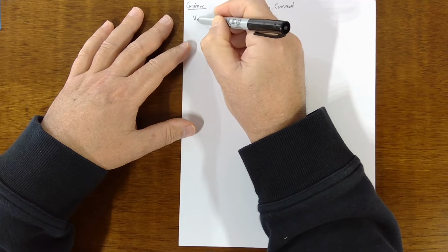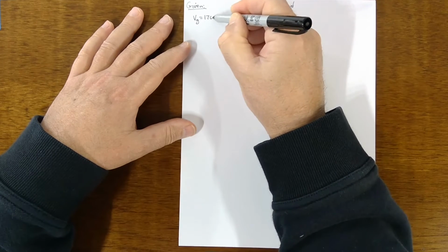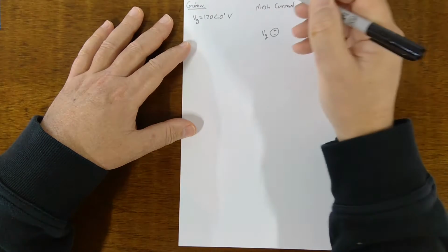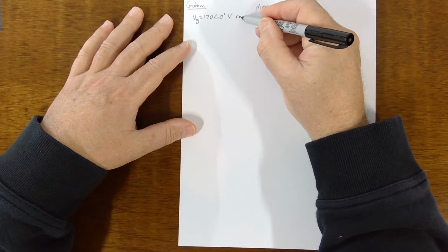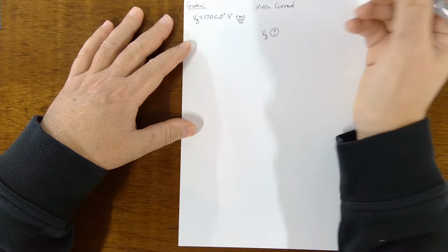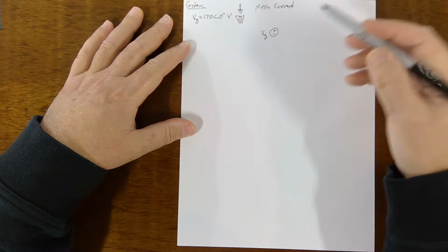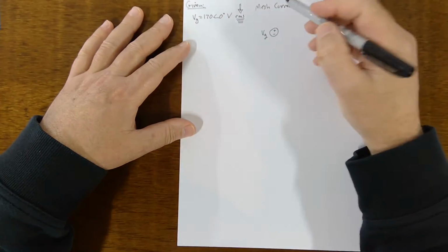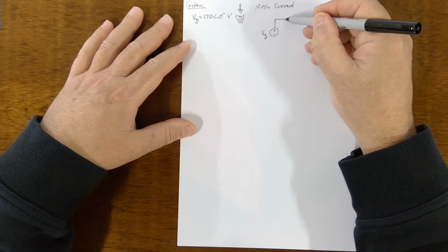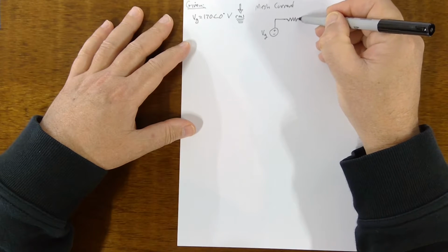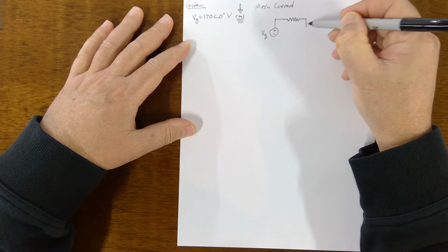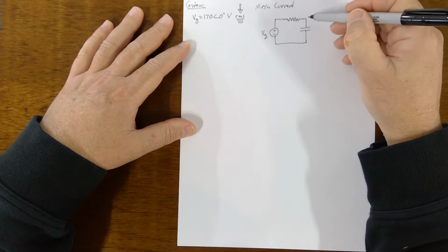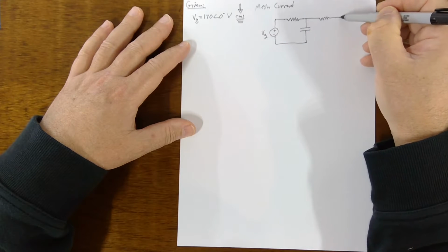So this is a sinusoidal voltage signal, 170 angle 0 degrees, giving us a phasor, and this is volts. Okay, this is RMS. I'm going to put a bunch of arrows and stuff. That's kind of important. So this 170 is an RMS value, not the peak value. And remember, RMS values, their whole point is to make power calculations easier in AC circuits. At least that's the way I think of them.